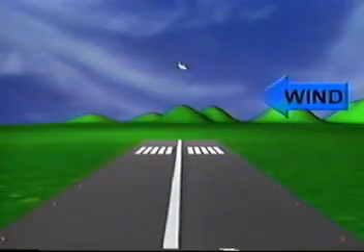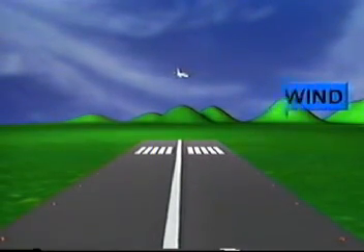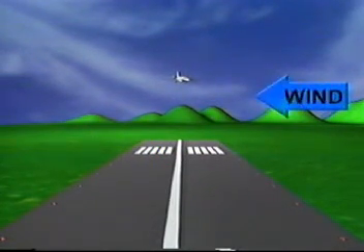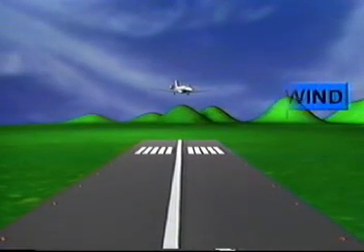Windy approaches. High-intensity surface winds are usually accompanied by turbulence and gusts. The problem then is to have a speed margin capable of covering any drop of aerodynamic speed due to wind change. Wind shifting and changes of intensity may require thrust changes. However, these thrust changes must be done at the proper timing and magnitude, as we have discussed before. Remember that jet engines respond slowly to acceleration requirements when compared to turboprops.